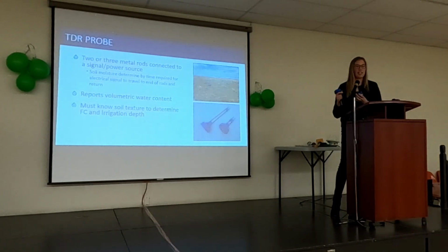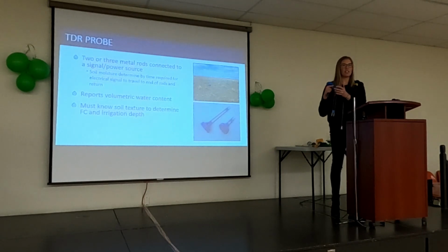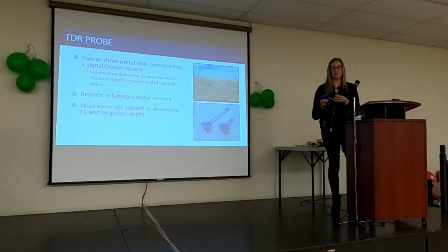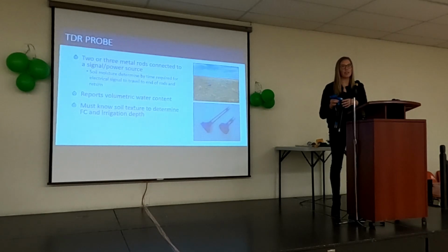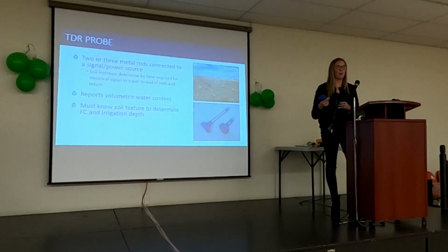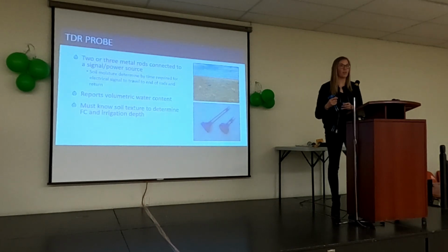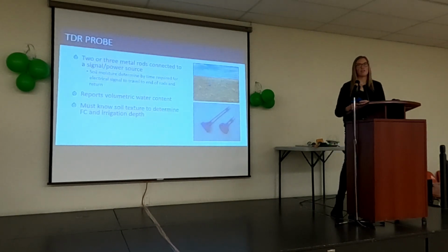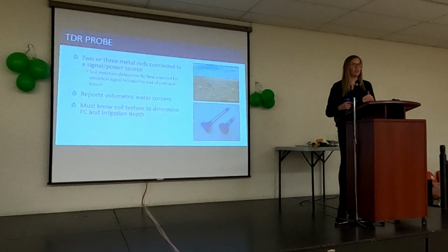These probes are also really nice. They have a wireless capability built into the top, so it's pretty straightforward. You just insert these into the soil. The data is transmitted to either a desktop or a cell phone application, and then we're getting fed the data output every hour and it's reported as volumetric water content. So there's not that need for all of those other conversions until you're going to calculate irrigation depth.